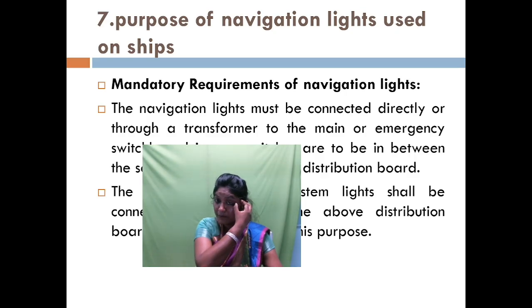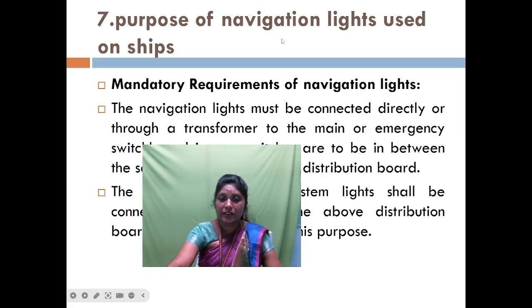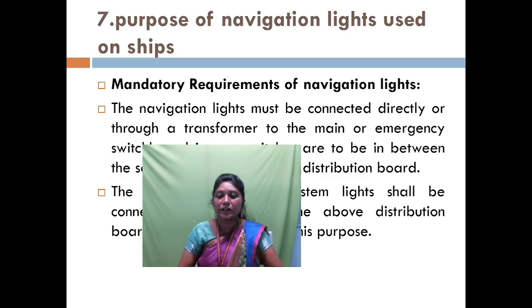Now we are going to see the navigation light. What is the purpose of navigation light? For ships there are some mandatory requirements for providing this navigation light. The navigation light must be connected directly or through the transformer to the main or emergency switchboard. There are no switches to be in between the source and the distribution board.